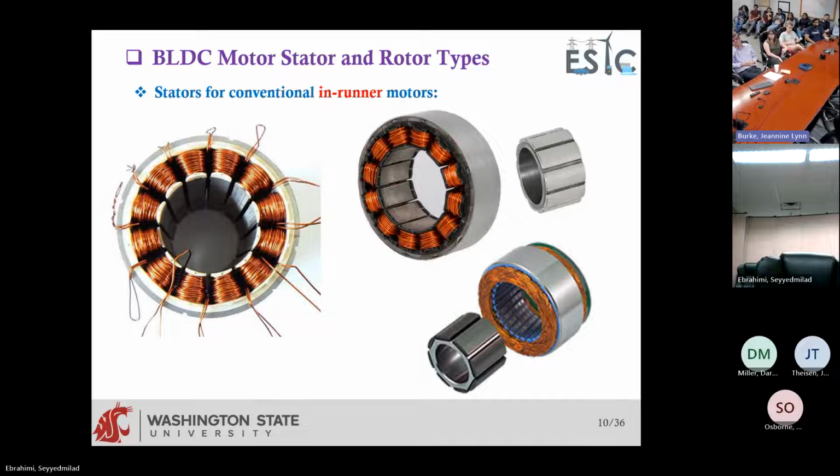You can also have what we call distributed winding. I'm pretty sure that you're partly familiar with this from your machine course, how we wind a stator winding sinusoidally. Depending on the application and how much you want to pay for it, they come in different configurations, but these are very easy to configure. This is also the permanent magnet rotor that goes in.